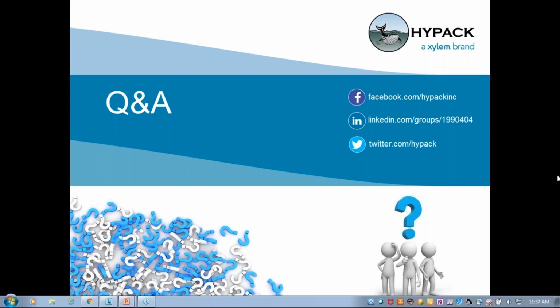What type of design templates should we use in DredgePack and where do we load them? Okay, great question. Well, I guess it kind of depends. If it's a more simple type of template, I would make it an advanced channel design. I'd make my nodes, faces, and any zones, and I would load that in DredgePack under chart channel. You'd load the CHN there.